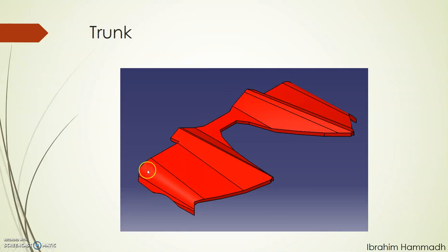Once this was done, that sketch was translated to a distance of about this edge to this edge, so that you had two base sketches. And then features were added to the second sketch so that they were representing the far edge of the trunk. Once I had two sketches, I connected the two of them using multi-section and using splines as guide curves, which can be seen here. And once that was done, this part was converted to a solid using closed surface tool.